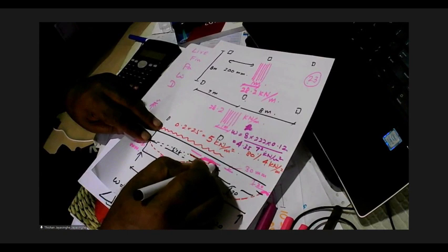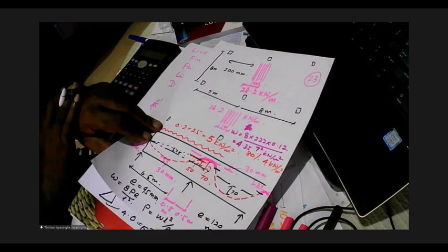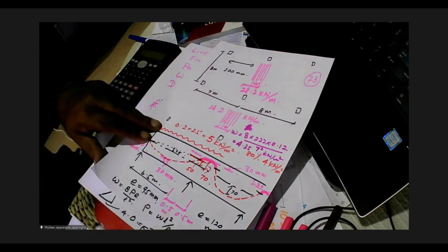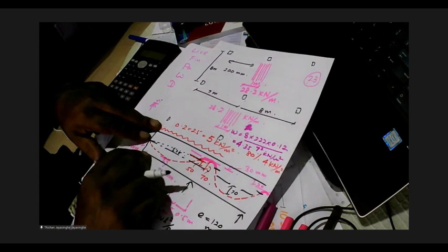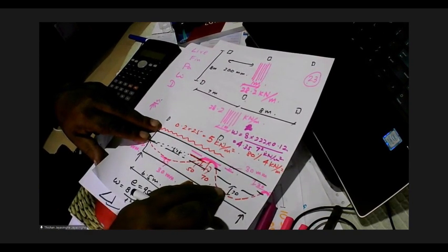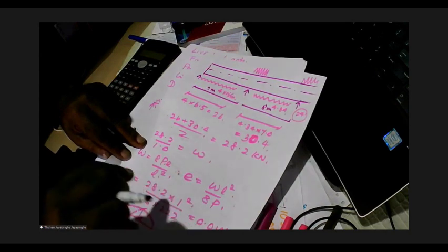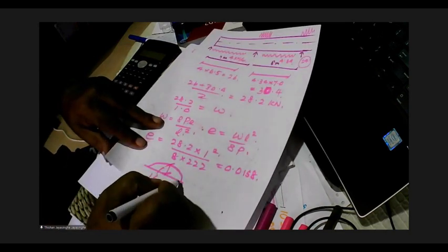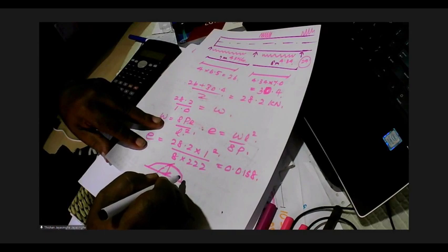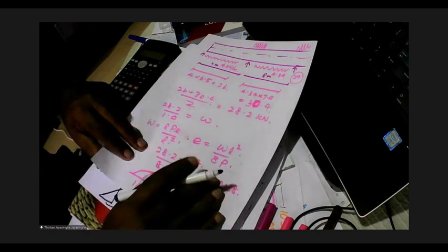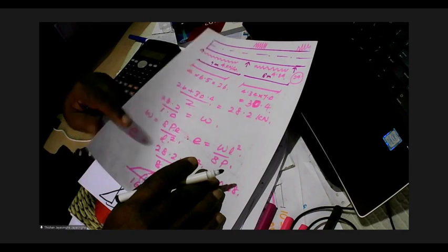Those upward forces can be transferred over a short distance as a band, and then you will find the pre-stress needed in the tendon cables per meter width. And once you find the pre-stress needed per meter width, we can work out the curvature that we need over the support. So that will give us almost a flat plate, and then